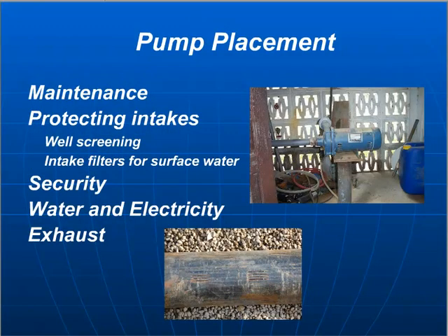Again, I see that this step is a lot of times overlooked, and at the TAC presentation, the final presentation with your technical advisory committee, it becomes an issue. So it's something to think about up front and not overlook. I worked on a project where the project was at the point where the pump was being installed, and I think it was a three-phase pump, even though the source electricity was single phase, and so obviously that was a big problem and required a lot of delays in the project.